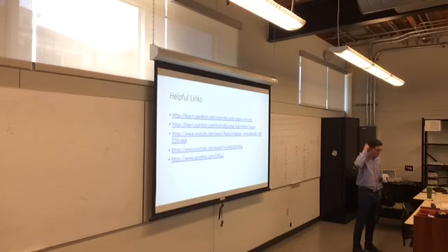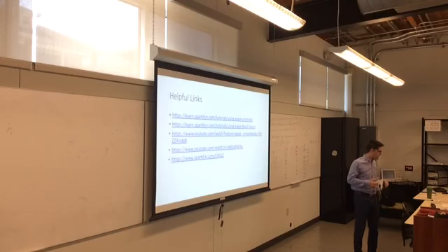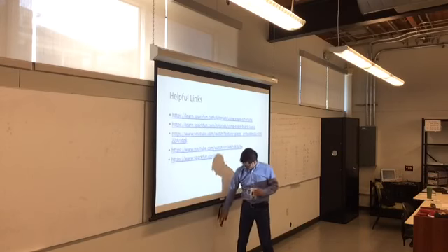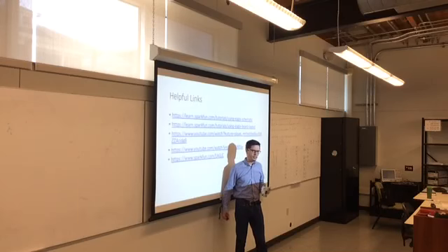from your system. If you get really stuck, we have a logic analyzer. You can check to see if you're generating a clock signal. You can take a multimeter and check to make sure that you're lowering the chip select line. If you never actually lower the chip select line, nothing ever happens. So there are a couple tests you can do. But this ends what we've got on that exam. It'll be the UART, it'll be SPI, and it'll be PCB design.